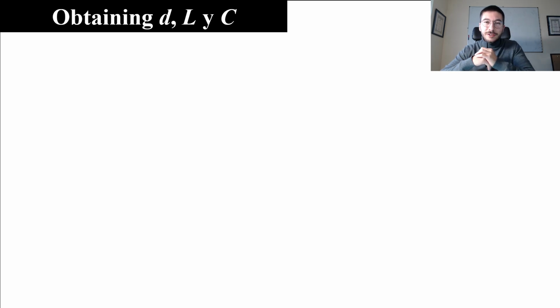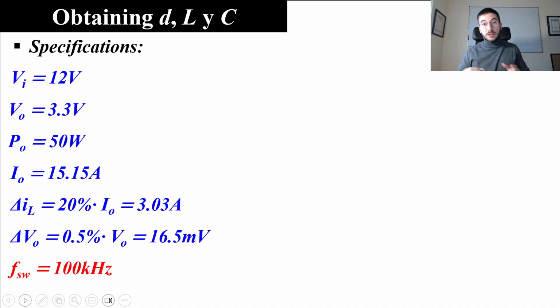Hi, we are going to start with the buck converter design, and for this video we are going to generate the simulation file of the LTspice circuit, and we want to work under very ideal conditions. So the first step is to obtain the duty cycle, the inductance and the capacitance that we need for the circuit, and to do that we are going to use the specifications that we set in the previous video.